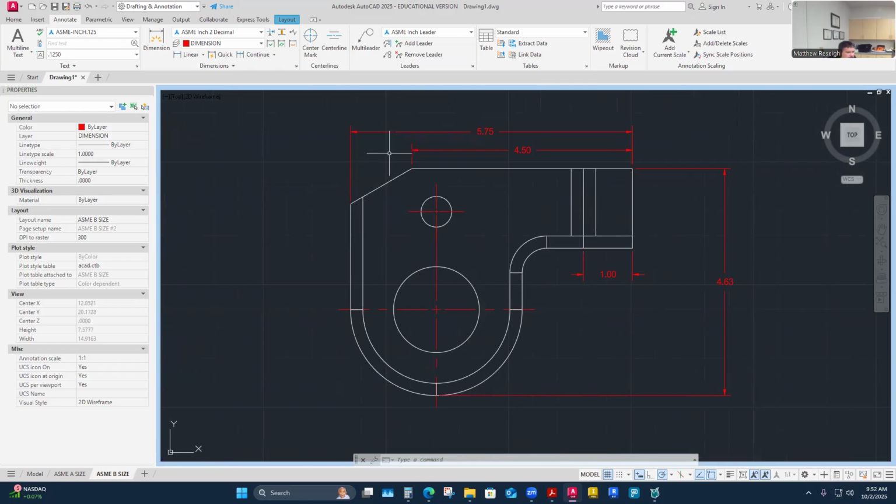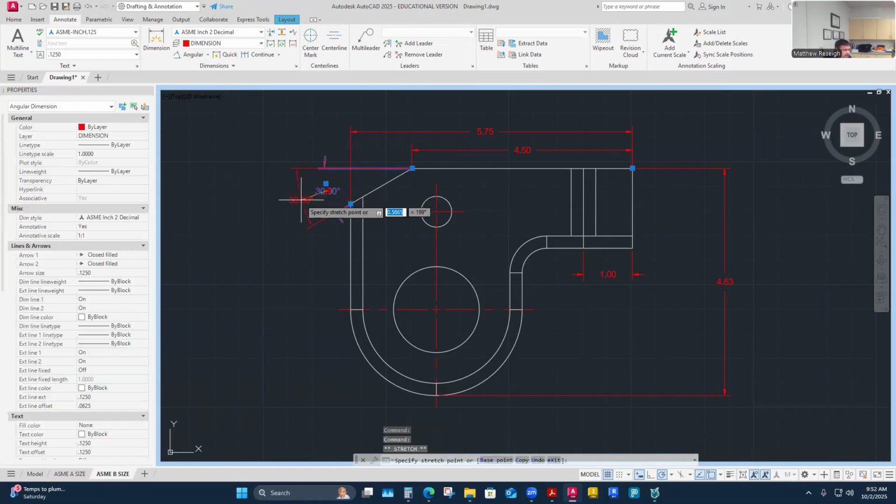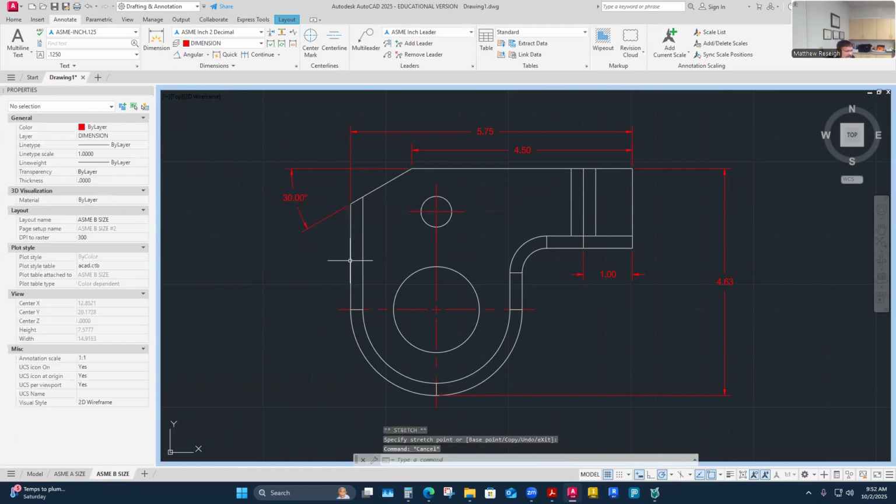And the other thing that ASME likes, instead of a miter dimension, is that you might do an angular dimension here. This is maybe a good practice. I worked for a lot of places that did these, and I think I've explained this before. A lot of places liked this kind of dimension, and maybe I would call it a reference dimension because it's just nice-to-know information. But maybe I wouldn't. Maybe it's not the most critical part of this. I don't know. ASME likes these to be point-to-point defined.